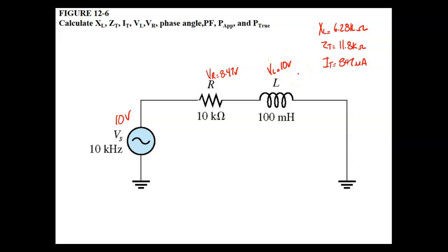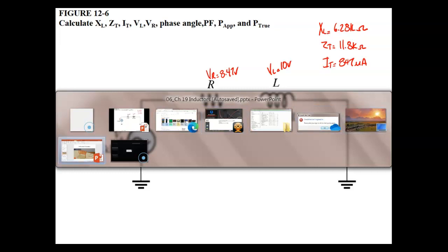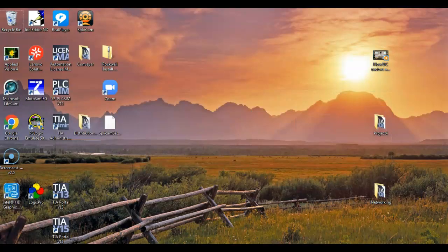So what we're going to do now is check our work. When I add these two together, it should be 10, but we're going to use Pythagorean's theorem to add it. And if they don't come up to be 10, then we know we've done something wrong somewhere, right? And hopefully they showed you how to do that even in DC.